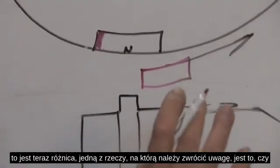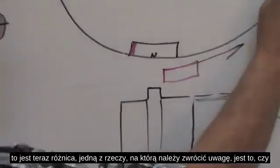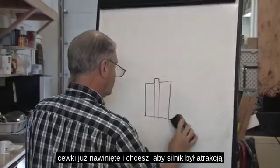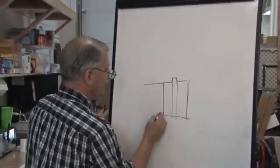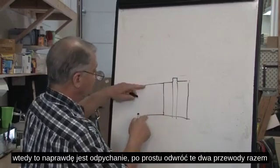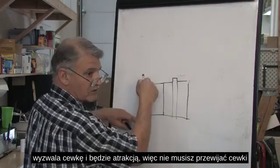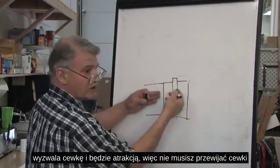So that's the difference. Now, one other thing to point out to you is if the coil's already wound and you want the motor to be in attraction, and it's really in repulsion, just reverse these two wires along with the trigger coil, and it'll be an attraction. So you don't have to rewind the coil.